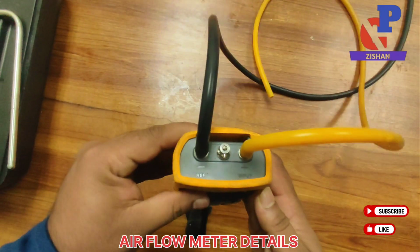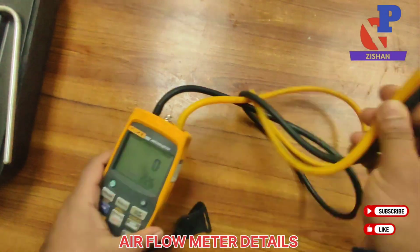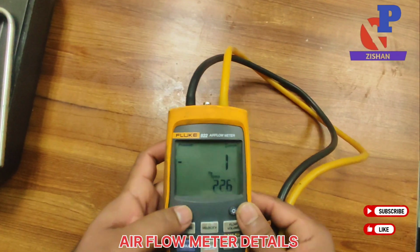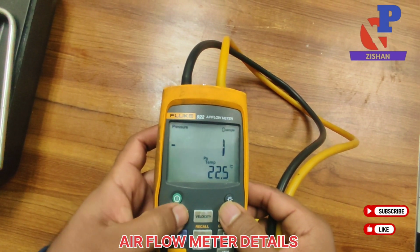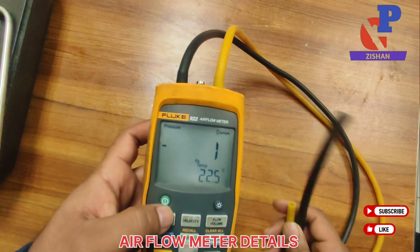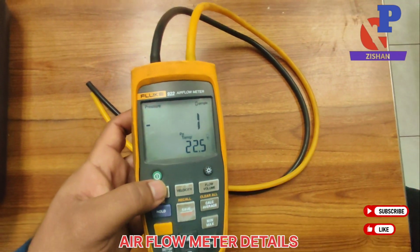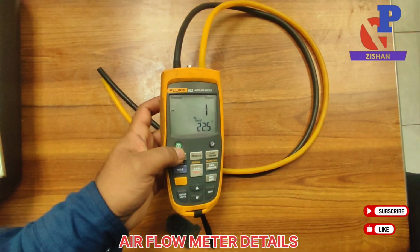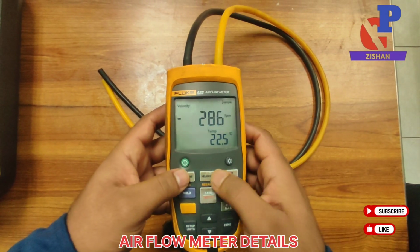After connecting both pressure hoses, the positive and negative, we can take the differential pressure across the filter. On the filter side there is a pressure drop, that's why we have to connect the positive hose before the filter and the negative hose after the filter. After that we can take the differential pressure reading across the filter.